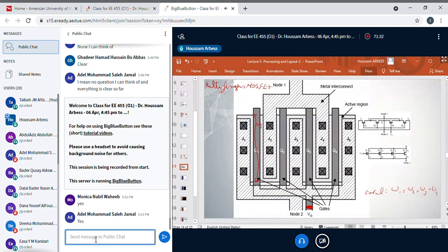So I will call it W1. Okay? So W total here is W1 plus W2 plus W3 plus W4. As I said, the area optimization is coming from using mini junctions as common junctions. So instead of having two junctions, one for the drain of Q1 and one for the drain of Q2, I'm using only one junction. In this way, I'm optimizing the area.